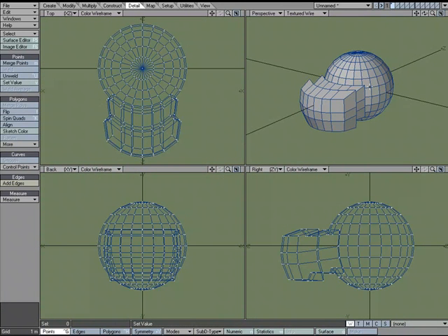set value, and it's a quick way to set the value for either X, Y, or Z axis for selected points or polygons. And what I usually use it for is to make sure that something is on 0x, 0y, or 0z, but you can type in whatever value you want and you'll know that it's exactly where you want it to be using set value.